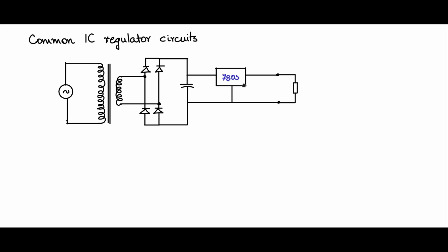So let us say if I use 7805, which means a 5 volt regulator. This has the in terminal, out terminal, and the common terminal, and here you will have 5 volts at the output of 7805. You should have a minimum differential delta VIO of at least 3 volts, which means that here the voltage should be greater than 8 volts. So when you are designing the turns ratio, you should see that at least under VI min condition, you get 8 volts at least.